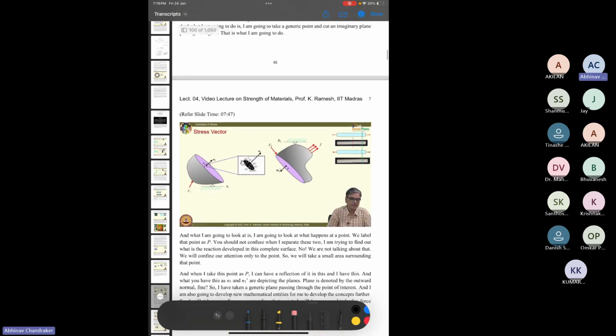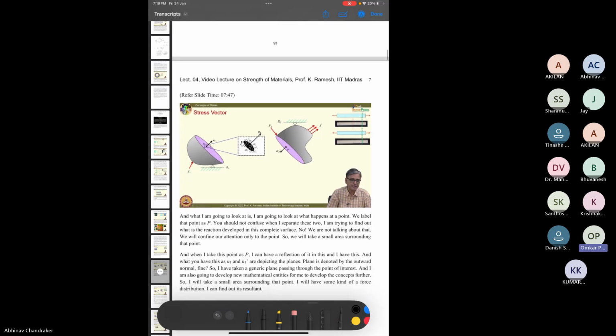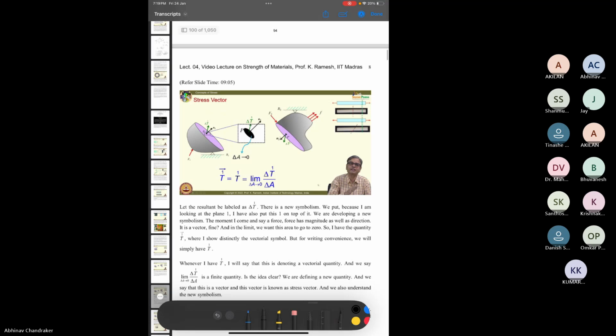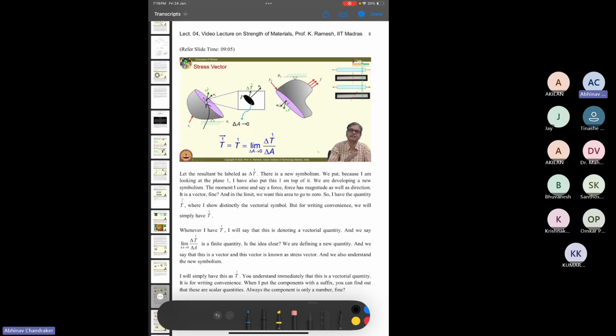So now let's move to understanding how we can mathematically represent the stress state at any point in a material, so that we can better work with the stress values which the material will be experiencing. For this purpose, let's assume we have this kind of a body and there's a point on it where we want to know the stress state. So we have cut it on a particular plane, and the stress vector, that is the force vector which is experienced at that point if you cut it in this plane, let's say it is delta t,